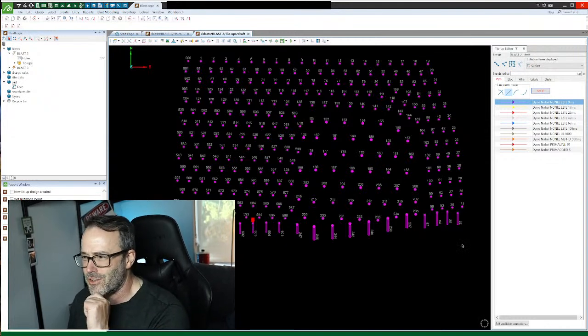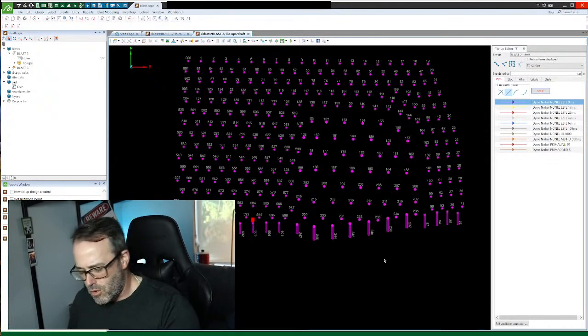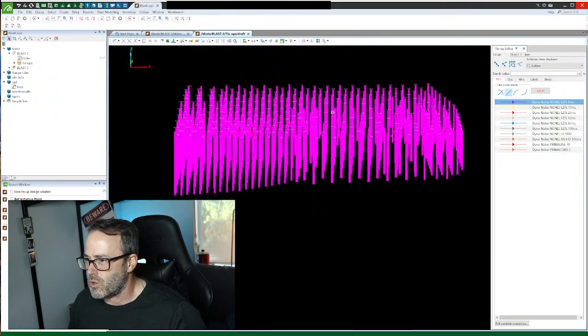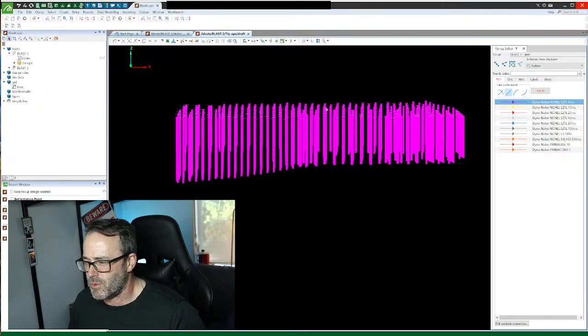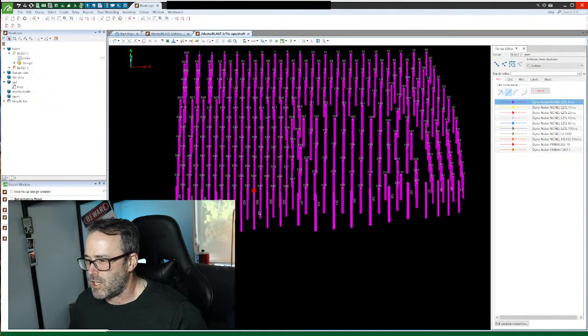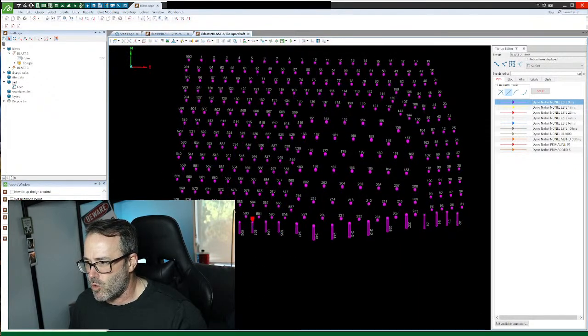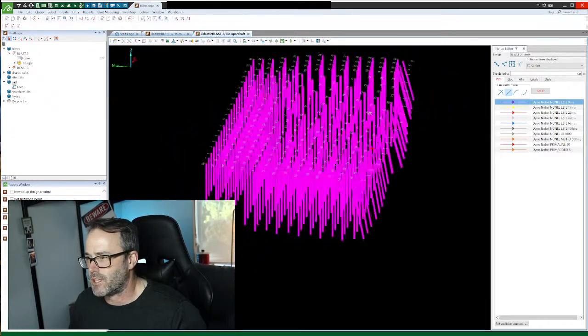And you're sort of going, do I want to use the smaller holes, or do I want to use the larger holes? And then you might say, I've got a ramp in that as well, do I want to fire from the ramp area first? And why would I be initiating first movements of a hole on a ramp grade, trying to break that toe out? So it's probably better to work over here and start over here, looking at that in a three-dimensional aspect.